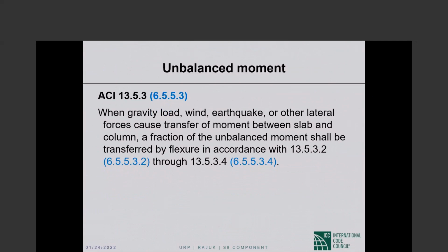Now we come to the complication of flat plate design, I would say. Unbalanced moments. When gravity load, wind, earthquake, or other lateral forces cause transfer of moment between slab and column, a fraction of the unbalanced moment shall be transferred by flexure according to such and such.